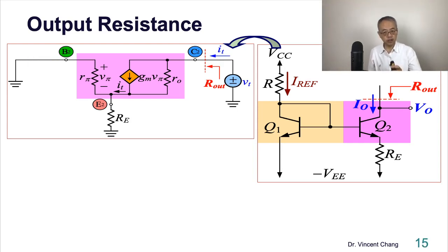So RE is negligible, and now you are facing this equivalent circuit. Let me ask you again: is the intuitive answer, RO plus RE, good? No, it's not good. Why? Because you missed two things. Put this down on your note. Number one, you missed R pi.